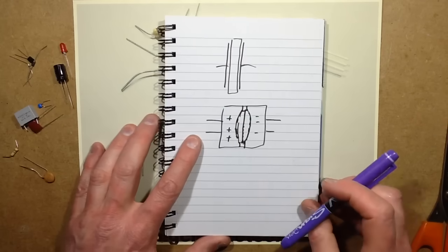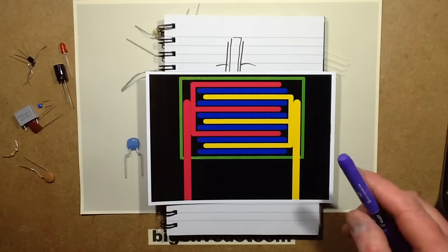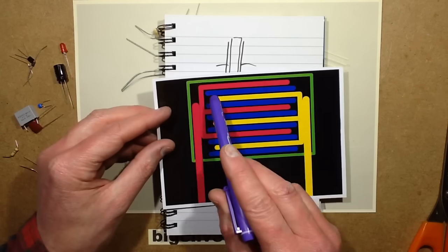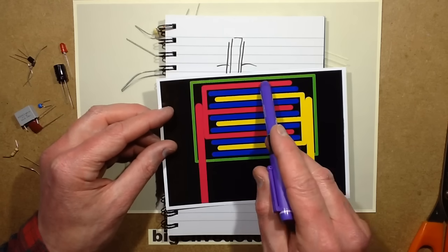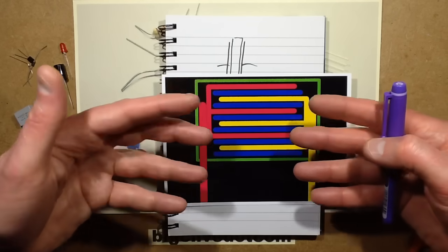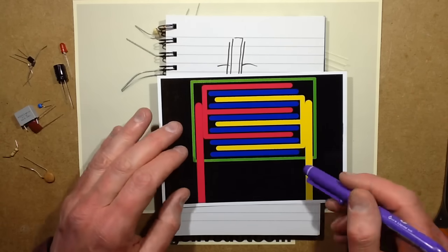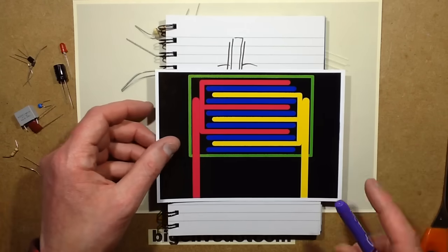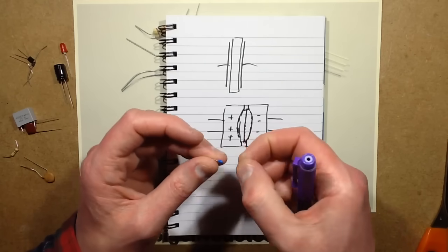To achieve the higher capacitance, they often make the capacitors multi-layer. So this is something I just printed out, designed on the computer in the printed circuit board design layout, but I just did it as a graphic. And if you can imagine that the blue is layers of insulation in the ceramic capacitors, and these are metallized plates, then by alternating the poles, creating a comb of them with insulators, and then putting a metallization down the end to connect them all together, you can create quite a large capacitance in a small area just by making it a multi-story capacitor, so to speak. And the layers of insulation in these are still going to be super thin. You'd need a microscope probably to see all the layers.